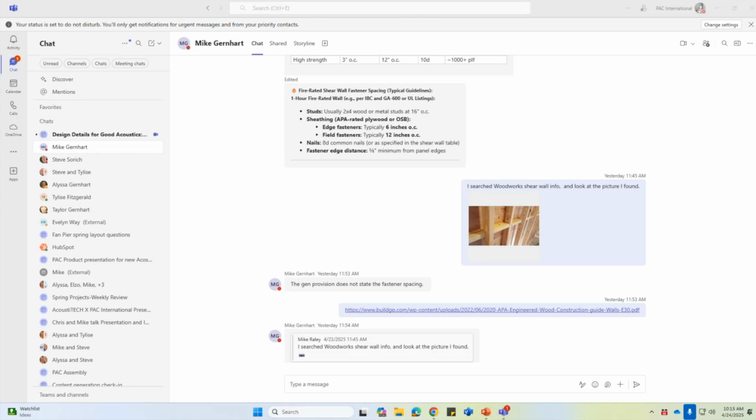Yeah, sure. So first off, if we're going to compare mineral wool and fiberglass, we want to be specific about where we're comparing them and in what context, right? In the context of fire, there are some significant differences between mineral wool and fiberglass. There are different uses for those within fire-rated designs. They have different requirements. They can do different things.